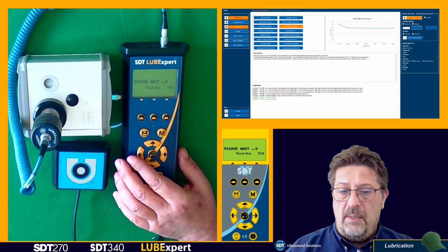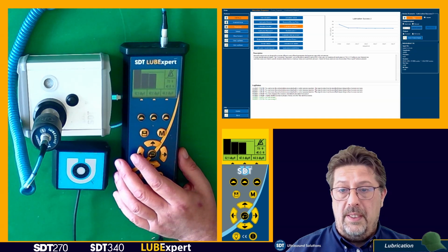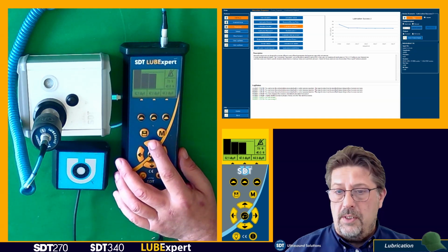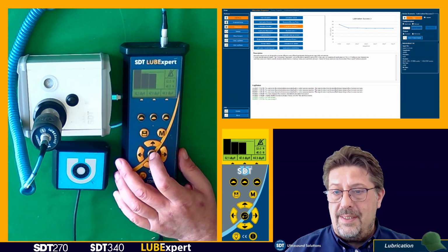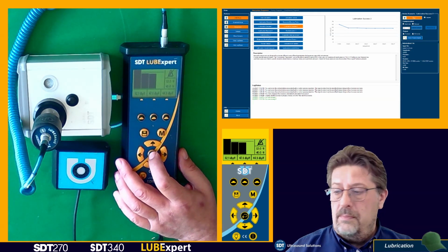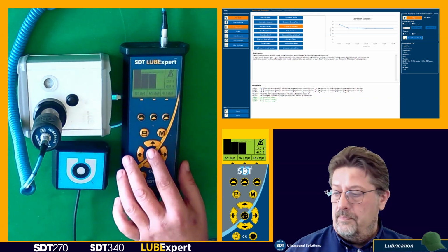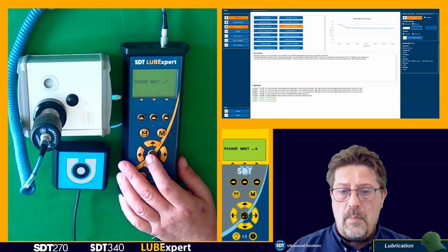Remember, I'm in the free mode, so decision about how much grease to put and when is mine. So I will just say to my LUBExpert that I put this time 4 shots. It's slightly going down still, so let's continue.